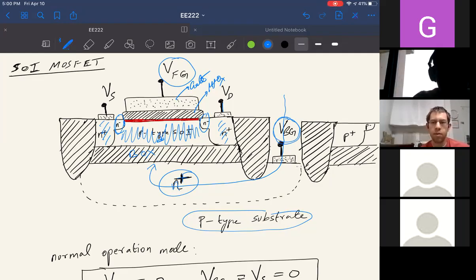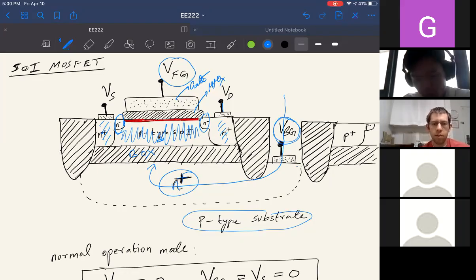Is that actually physically there, or is it like the buried gate that was shown in the FDSOI video, where it's not physically there, but it acts like that because of the oxide in the middle, the box? Yeah, so you need to somehow contact this. I mean, you need to somehow excite this capacitor, right? So you have this capacitor. The only way to do that is to contact this somehow, so you bring the contact to the top side because everything is connected from the top side.